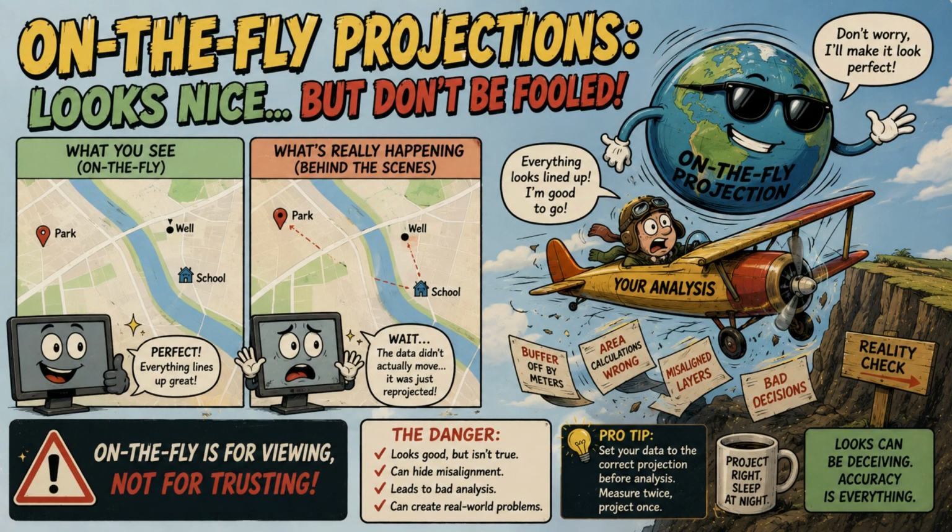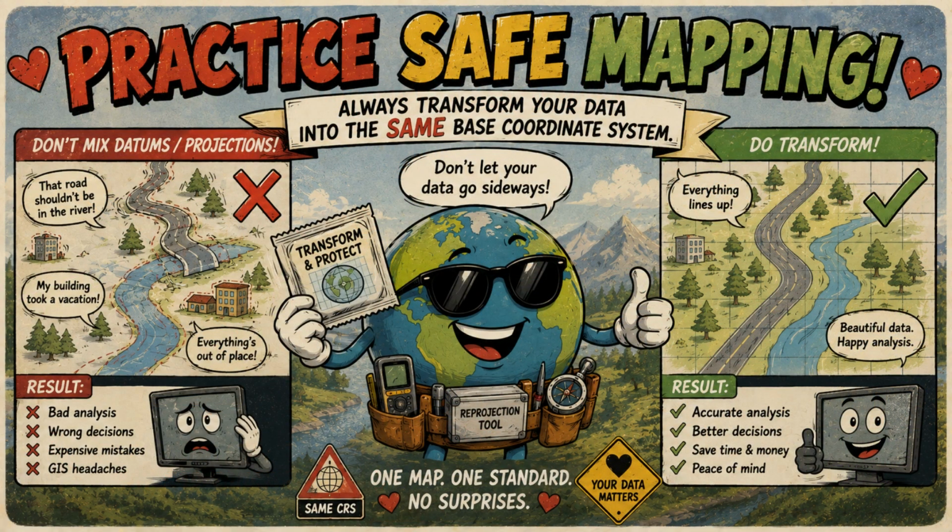So if you run a spatial analysis tool, like, say, calculating the total acreage of a forest fire, or determining if a chemical spill is within 500 feet of a water reservoir, and your datasets are not mathematically transformed into a unified datum and appropriate projection, the software will confidently hand you a completely wrong answer. You must manually verify and transform all your data into a single, appropriate geodetic framework before executing any analysis. That step right there separates the mere software operators from the true GIS professionals.